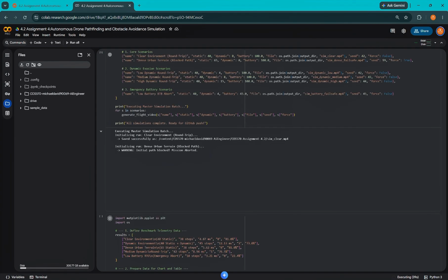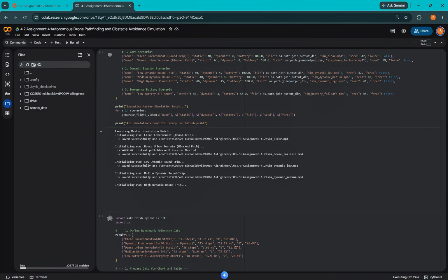As the notebook executes, it compiles our core navigation architecture. Global trajectory planning is handled by an A* graph search using an admissible Manhattan distance heuristic, perfectly matched to our orthogonal four-way movement grid. Controlling the mission lifecycle is our four-phase finite state machine, which governs the outbound delivery run, payload drop, inbound return transit, and emergency fail-safe aborts.